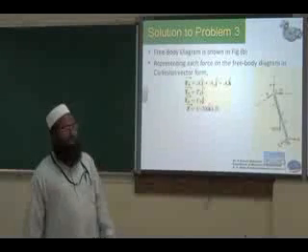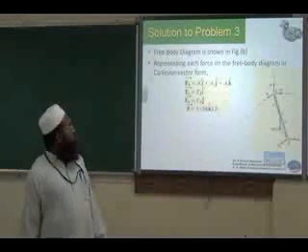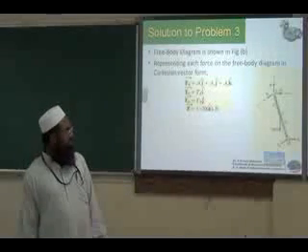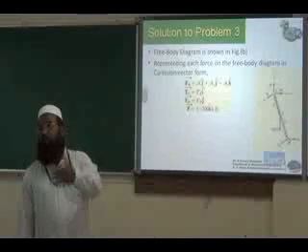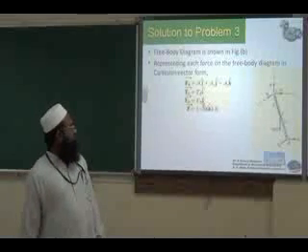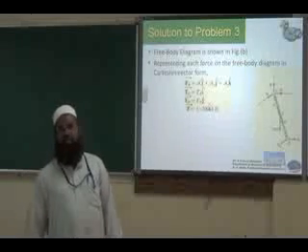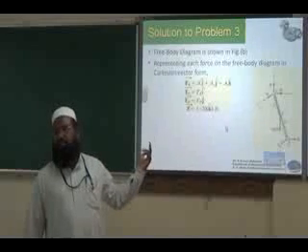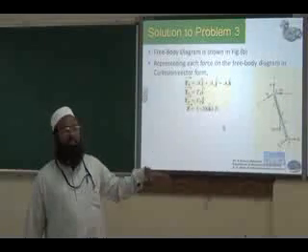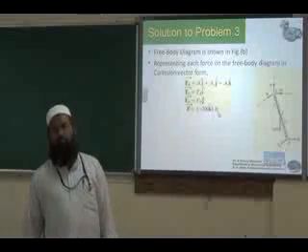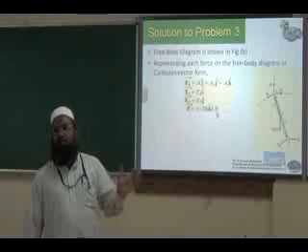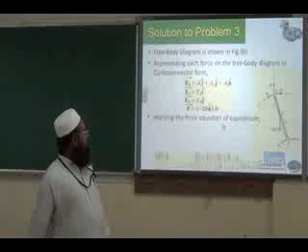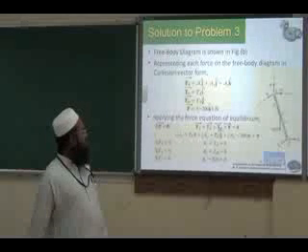Then TE is the force acting parallel to your x-axis, so you will have only TE I, unit vector I, x-axis only. TD is tension existing parallel to the y-axis, so TD J. And this force acting at point C is a vertically downward force parallel to the z-axis, so 200 K. So we have represented all the forces in Cartesian form. In order to find the moment, if you just take the position vector R cross F, you can find out the moment. So first we use the force equation.